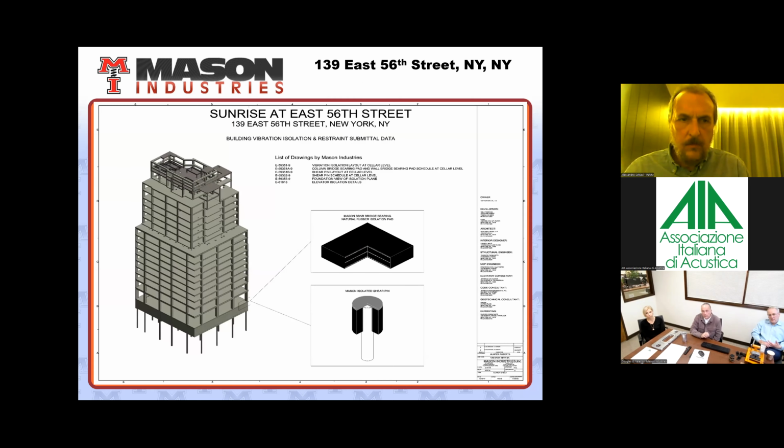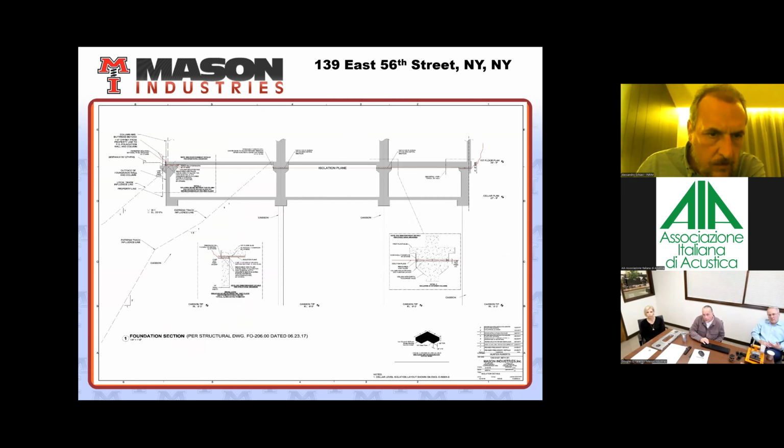That being said, last but not least, Sunrise is an 18-story building, typical isolation system. The critical point on this one is establishing the isolation plane. The isolation plane should be above grade so that you don't have any compromising vibration coming through the soil into the structure. So this is at the location right below the ground floor.